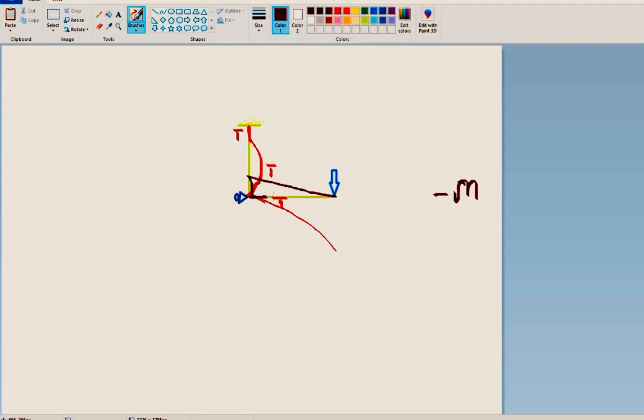And the tension side is this side. But here, if you see, tension is this way. Since this is pushing, there will be some additional reaction coming here, right? So tension will be this side. So the moment diagram, if you see it, will look like this. It's a linear line. This is also a linear line only, and there is this curve going. This is one curvature, this is another curvature. There is a point of contraflexure at this point. That's why the moment is 0 at this point. Okay.